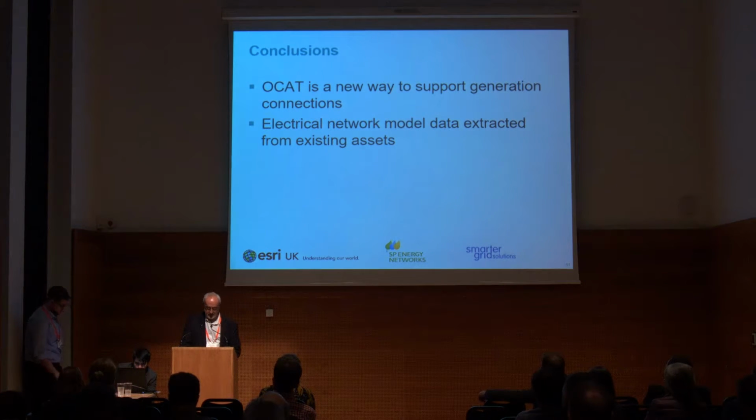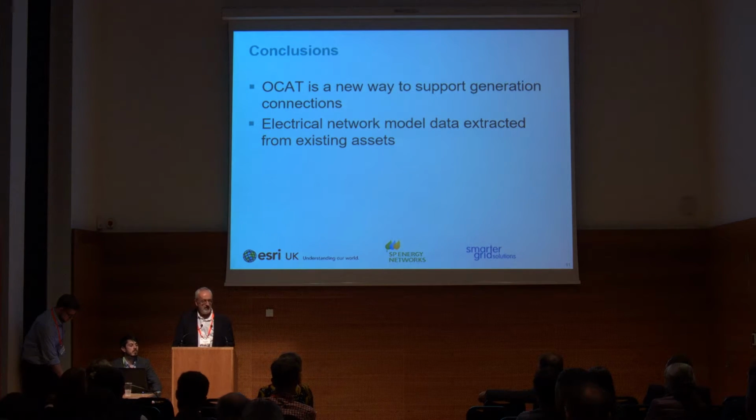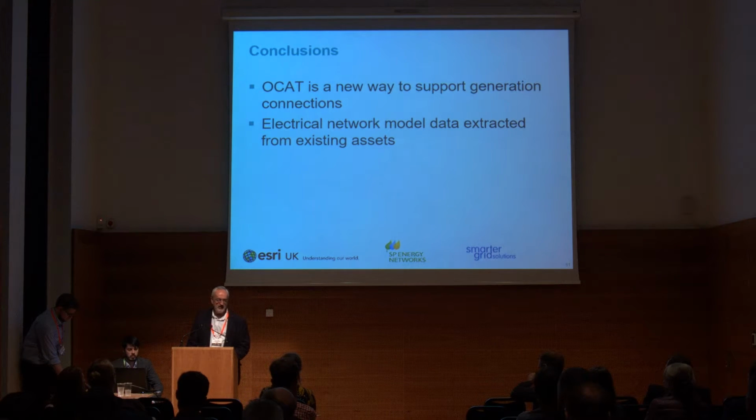These advanced modeling power flows are to make best use of existing assets. Evolve to model other technologies which Martin hinted on. Real-time, we probably move towards real-time thermal ratings of cables and transformers, which will give us even more capacity on the network. The active network management itself, on average, almost doubles the amount of connected generation that you can get on an average circuit or part of a system.